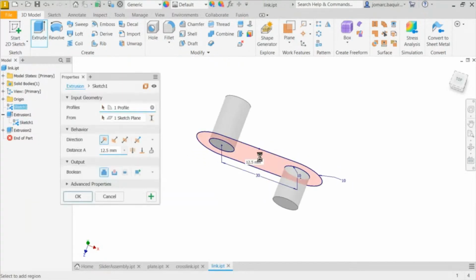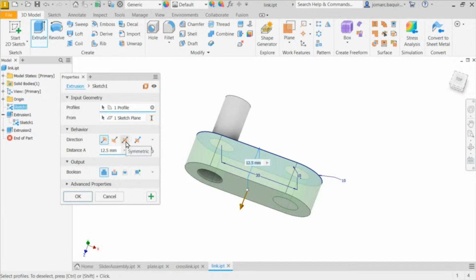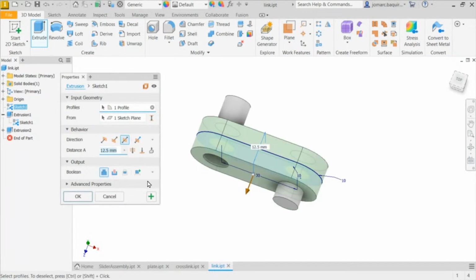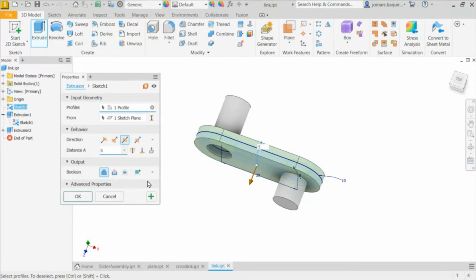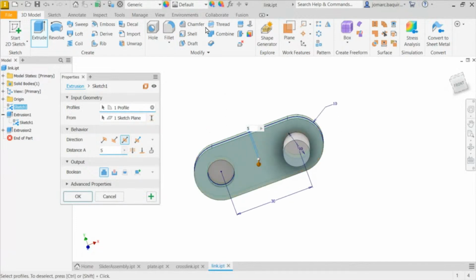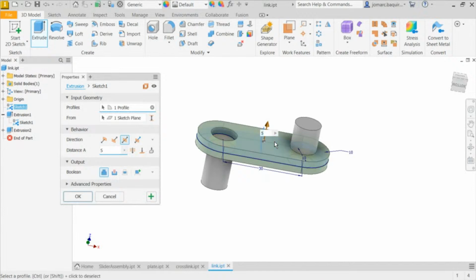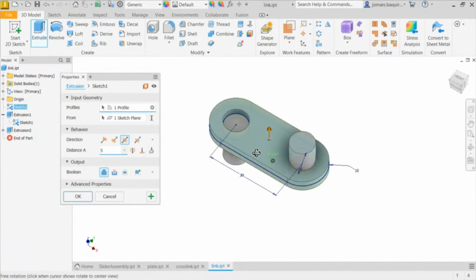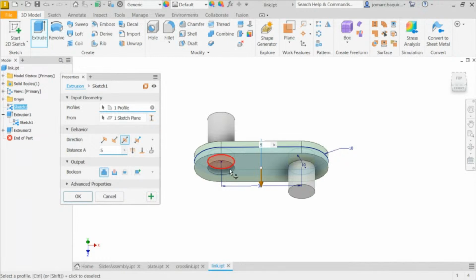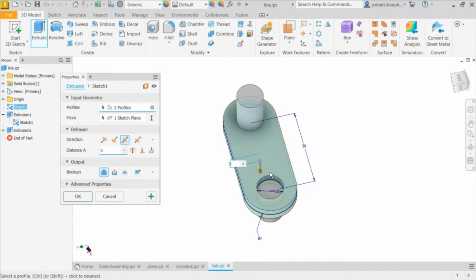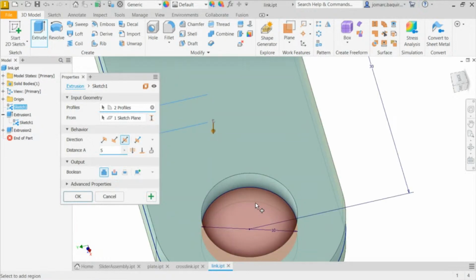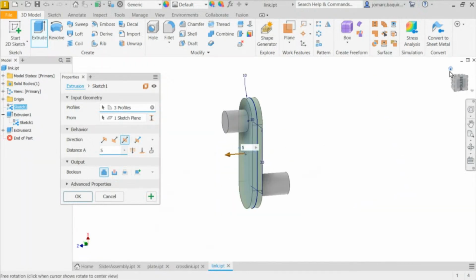And finally, hit E for extrude again, selecting symmetric. And once more, the thickness for this to be 2.5. But notice we have a hole recess here. So with that, I have selected one profile. I'm holding Control to add that profile. So rotating as well, holding Control, selecting this profile as well. So I have selected 3 profiles.